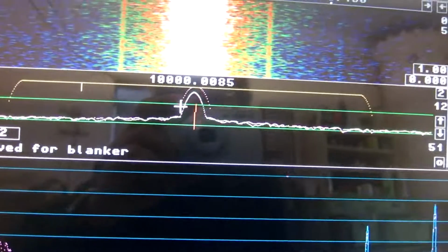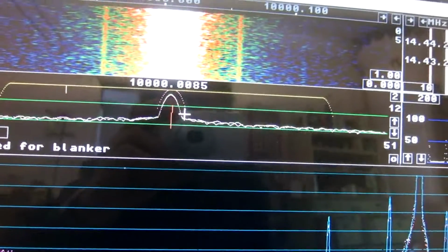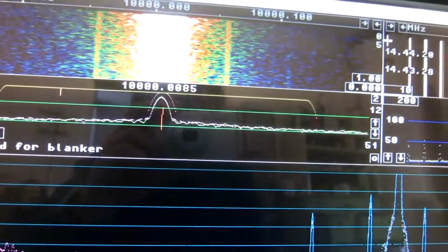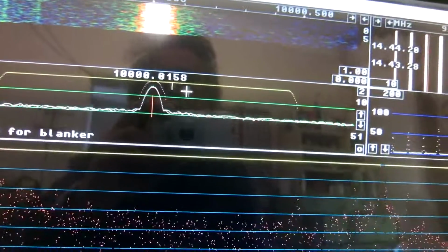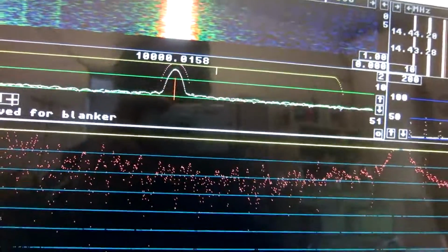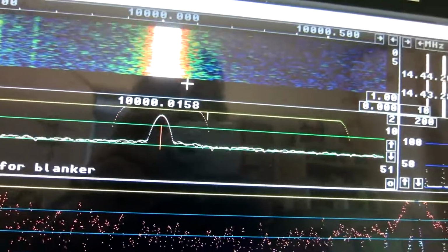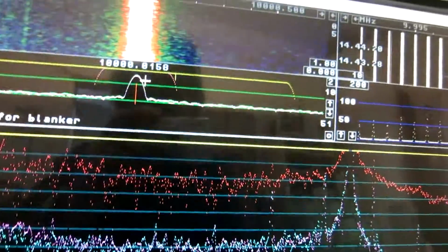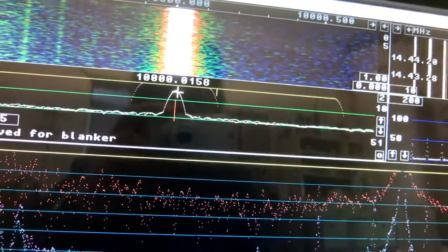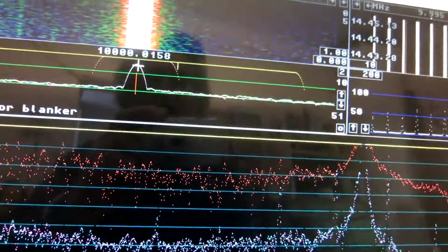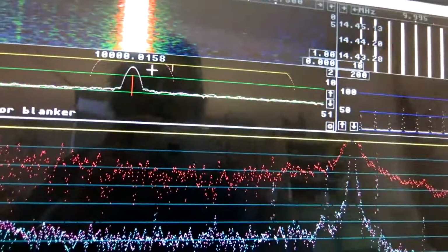The carrier is extracted through this narrow filter with a bandwidth in the order of 10 Hz. If I make this filter much wider, I can do that by changing parameters. Like this. Now this filter is about 200 Hz, which means that frequencies up to 100 Hz will be present in the reference signal I have, and that should remove phase modulation below about 100 Hz.